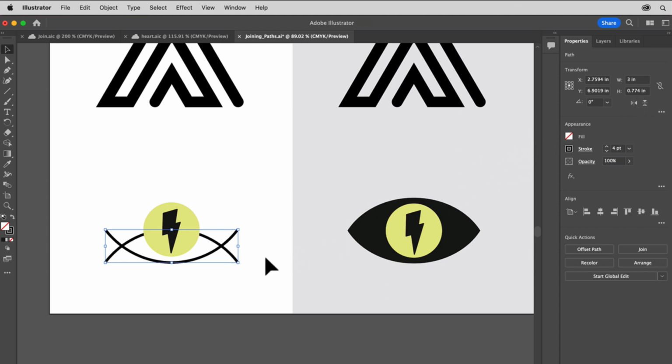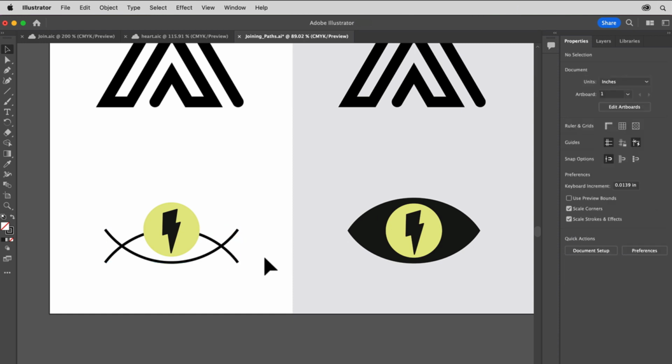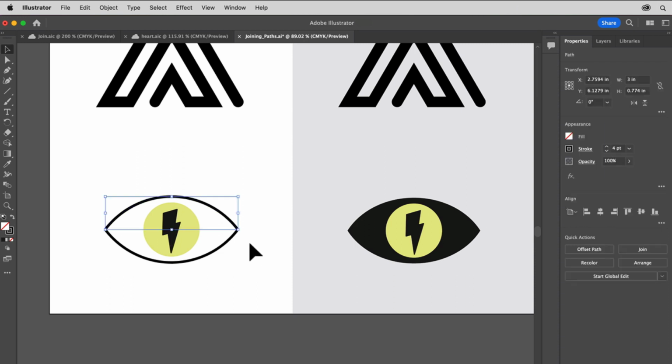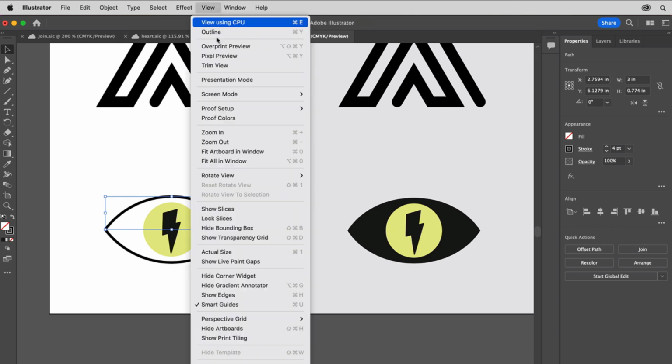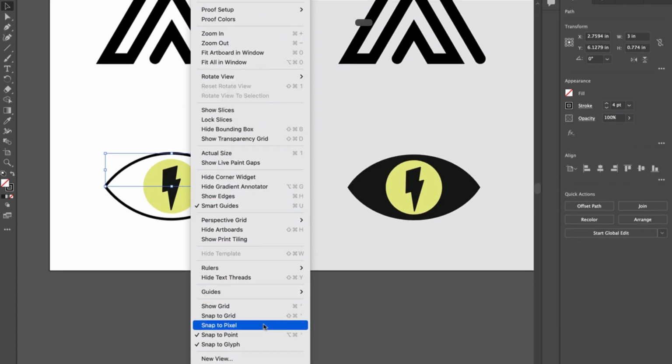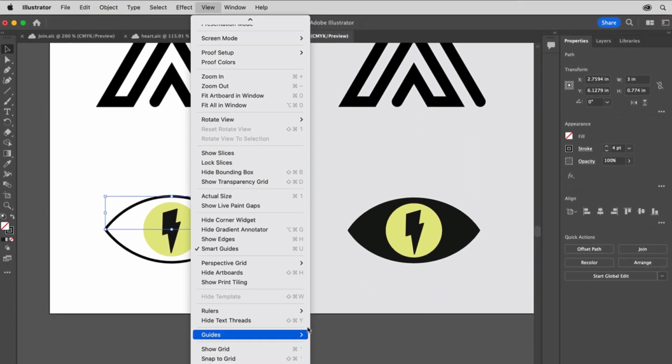Okay, now to get it into position. We want the endpoints of these two paths to overlap. So click away from this path to deselect it. We're deselecting so we can drag the path by the end without reshaping it accidentally. Drag the path copy by its end so that the end aligns with the end of the original path, like this. You'll see the cursor turn white when they're aligned, so you can let go then. If you don't feel the snapping and see a white cursor, turn on Snap to Point so the points can snap and align to each other, and then try it again.